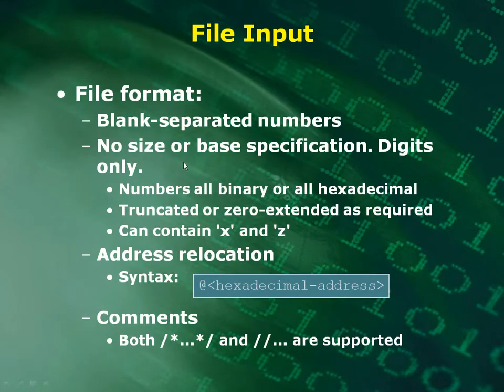Also, in the file format, you have blank separations between the numbers, and you cannot use a size or a base specification, only digits. And the numbers have to be either all binary or all hexadecimal. They're truncated or zero extended as required, and they can contain X and Z. We also have what's called address relocation, and this is the syntax for it. You put an @ sign and then a hexadecimal address. You can also use comments, and these should be familiar, or this format.